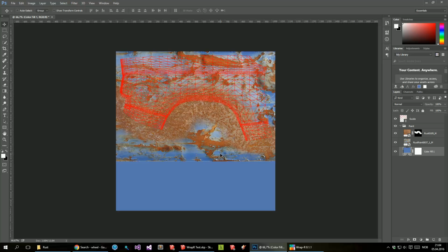I want a solid texture out of this with no transparency. Because once you add transparency to a texture, it takes more processing time when you render it. Even if it's just a single transparent pixel, it switches to rendering mode.